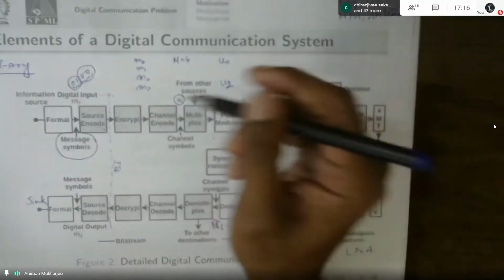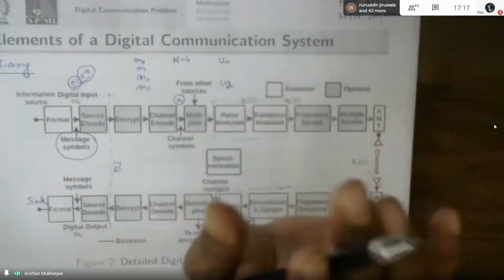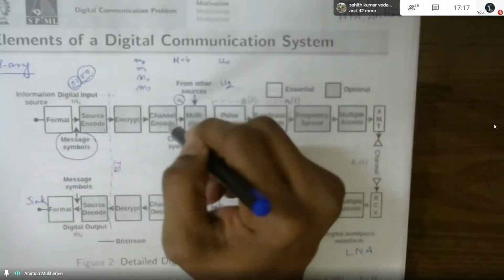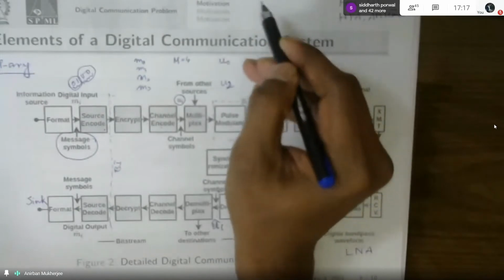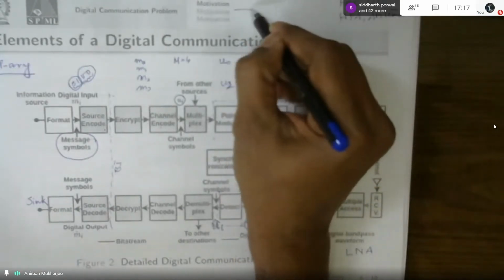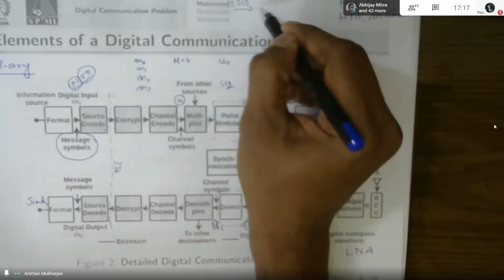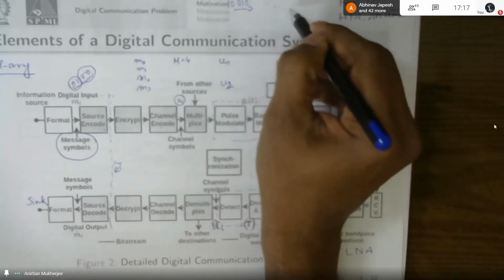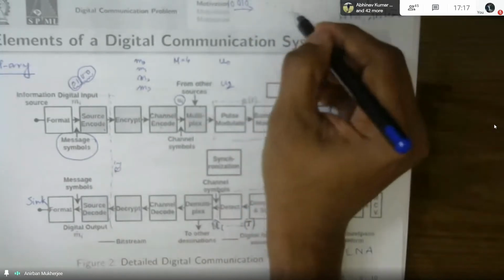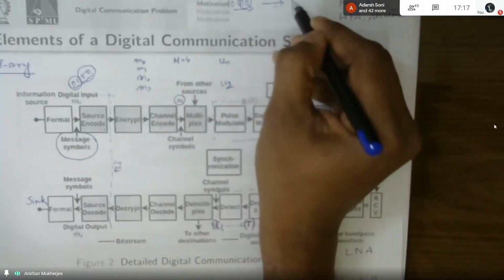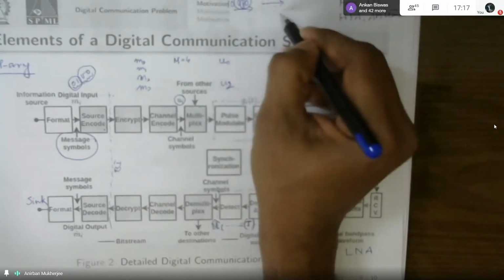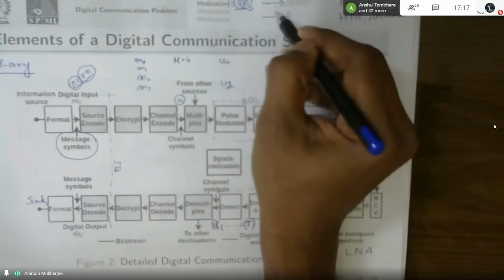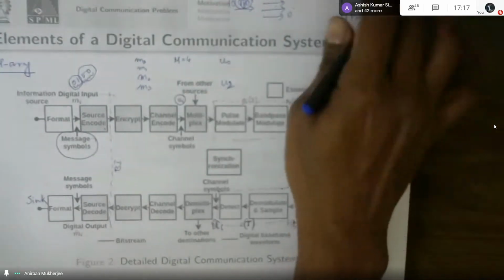Just as an example, say I am doing 1 bit together, M0 and M1, where the symbol is the same as the message. Instead of sending it without channel encoding, I first get a bit stream, say 0, 1, 0, 0, 1. Then I do XORing on the first 2 blocks and give an output. Similarly, for the next one I do an XOR and give an output, and for the third I give the XOR of the first and third.